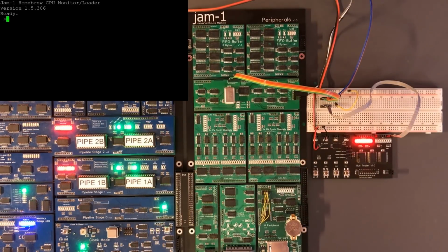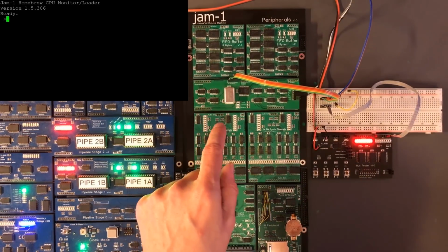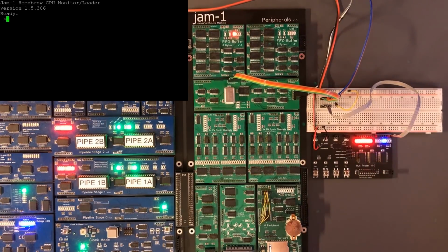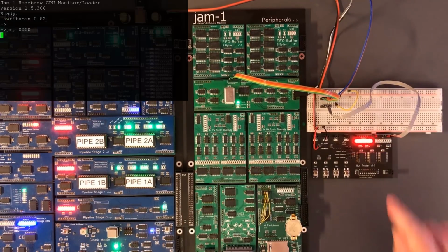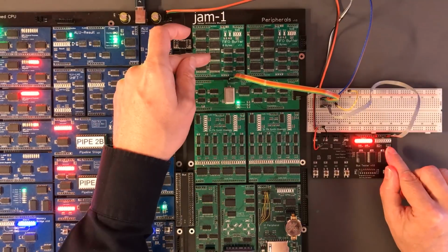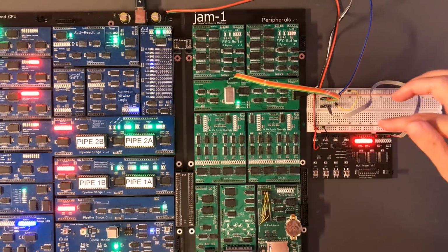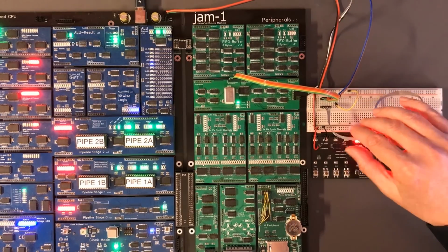I'm going to leave that stopped. Now we're sending some characters. So yeah, 1, 2, 3, 8. I've proven I can solder a header on. Get that test code back in. We have a 4-bit binary value for the number of bytes in the receive FIFO buffer, and we want to set a threshold in order to trigger the clear to send line.